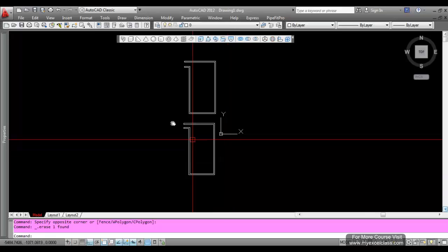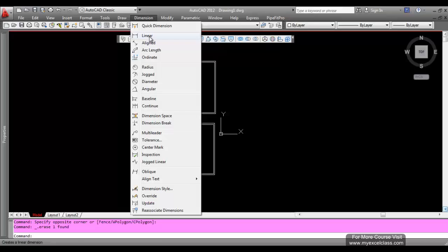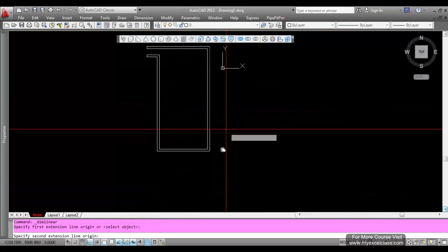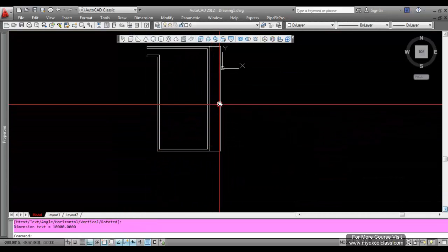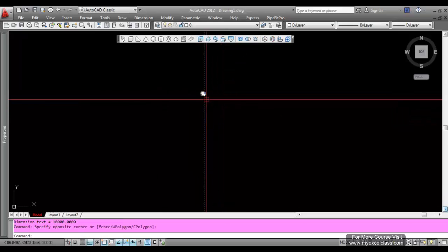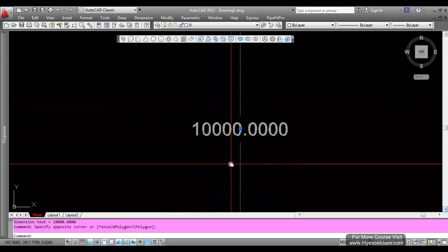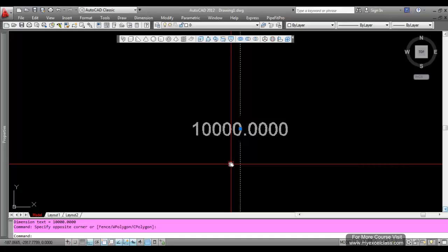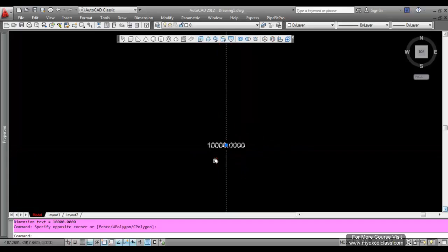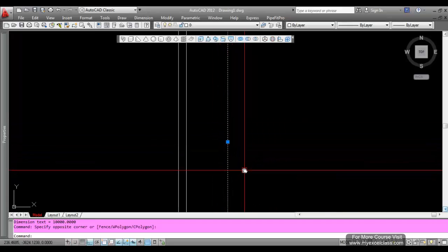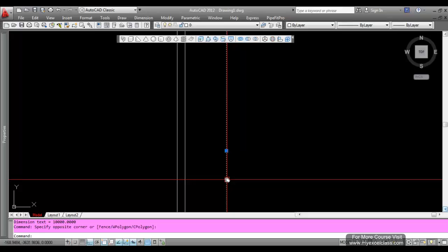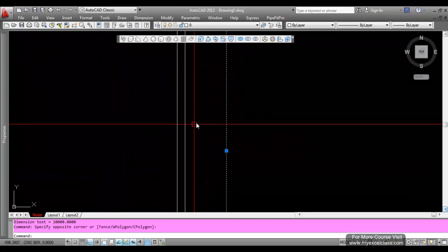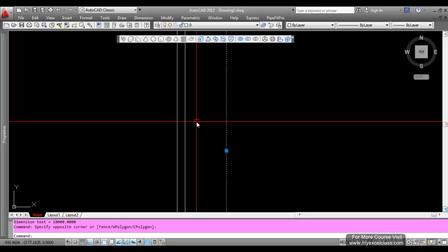Now the bottom one we have prepared based on left justify. In that left justify, what is the dimension? Exactly 1000. That is, outer to outer is 1000. So justify is very important whenever you make a project. By default, whenever you open AutoCAD, POLYSOLID gives justify center.